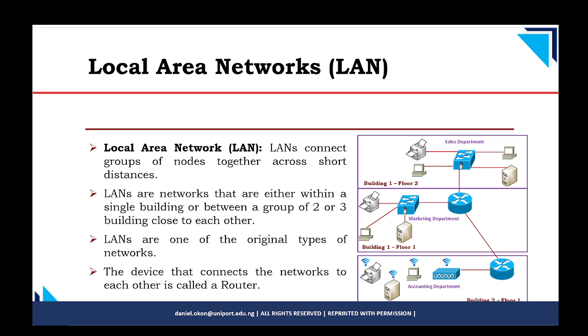So what usually happens in your hostels is that you go and tap light from light bulb to power hot plate or ring boiler. The next thing you notice is that the cable starts burning, and you now start asking yourself what has happened. It's because the network guy that was configuring that place told the place that only electrical lights should be connected there and not ring boiler, because ring boiler needs a very high type of cable.